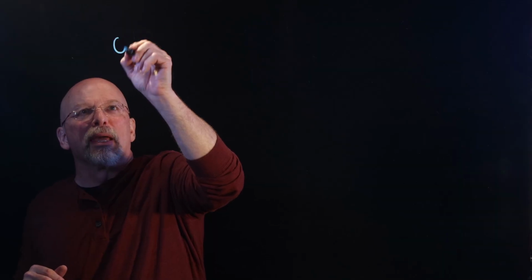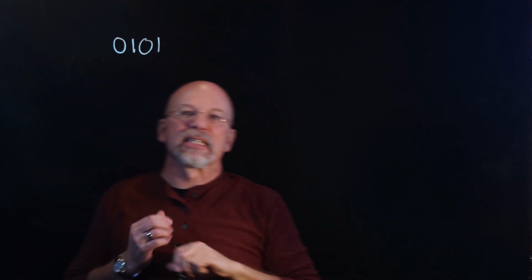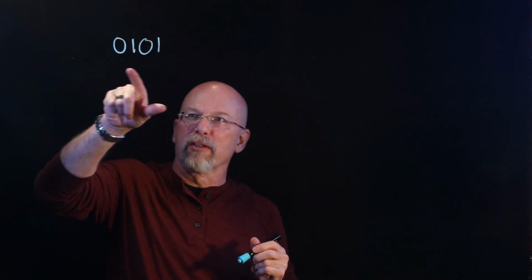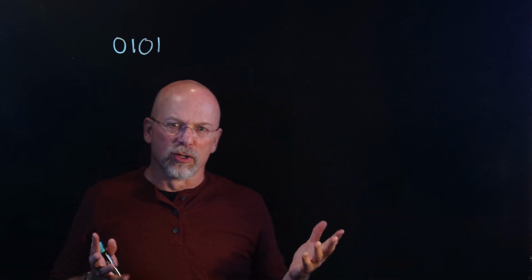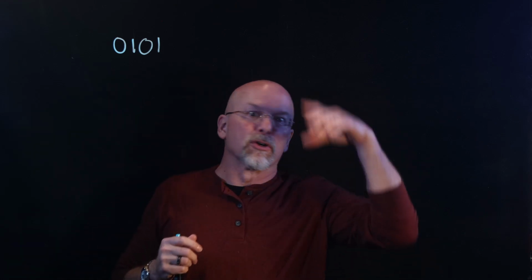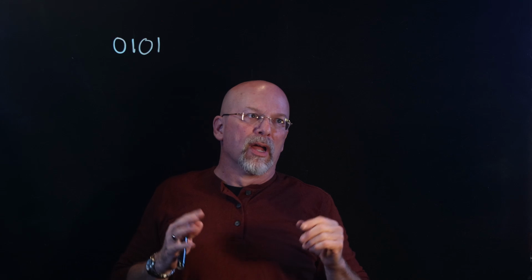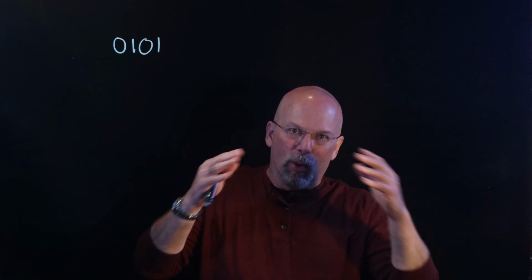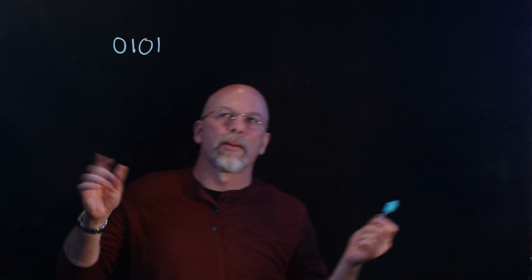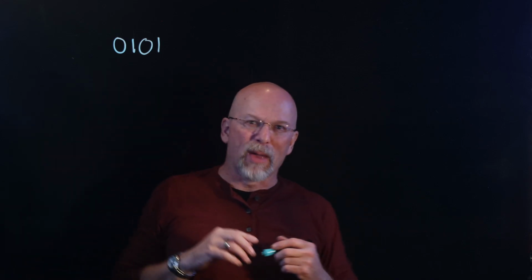What we're going to do is make a state machine that takes as its input the binary alphabet, and it's looking for the sequence 0101. This happens a lot whenever we're talking about digital communications. You're looking for a pattern of ones and zeros to trigger something, either the start of a message, or sometimes, if we get more than 4 ones in a row, in order to keep synchronization, we do something called zero insertion in order to verify that we're going to at least get some bit changes. There's a number of reasons why we would look for a pattern.